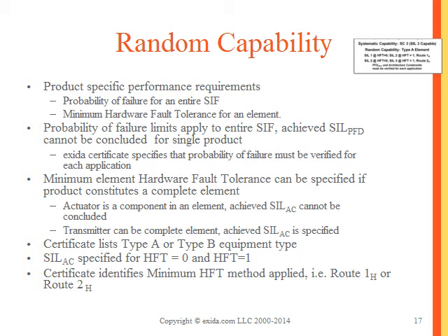As a rule of thumb, anything that uses a microprocessor or custom ASIC, application-specific integrated circuit, is typically a type B. Devices that don't use that, like a relay or a switch, tend to be type A. So transmitters and logic solvers tend to be type B.